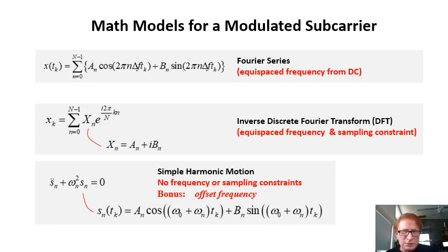That is, the digital sample interval must equal the inverse of the frequency separation. This use of the FFT for fast digital processing is what imparts the orthogonality constraint to the subcarriers, and not the ability to separate the closely spaced subcarriers, as we will show shortly.